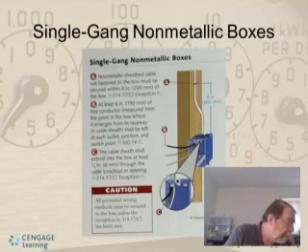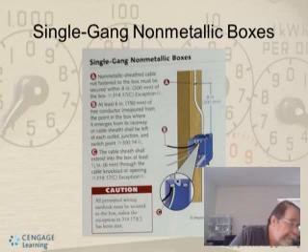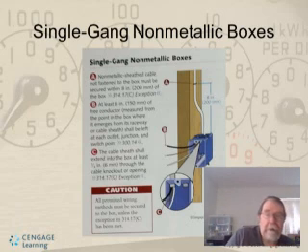Again, here's another single gang non-metallic box installation. You see where you're 8 inches from that staple up top. And there's also a height off the floor, but we may cover that later.